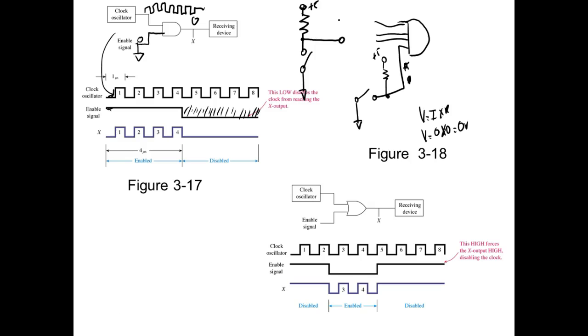Guys, this is what you've got to understand. A resistor only drops a voltage if there is a current flow through it. So a voltage drop would be I get less out than what I put in, right? You understand? I have no current flow through the resistor, so the resistor is not dropping a voltage.